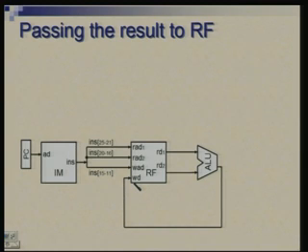So, you have one clock at which PC gets the value, and at the next edge of the clock the result of this instruction will get stored in the register file. Okay. And at the same time we will arrange, we will see in the next slide that PC will have to get a new value and be ready for the next instruction.